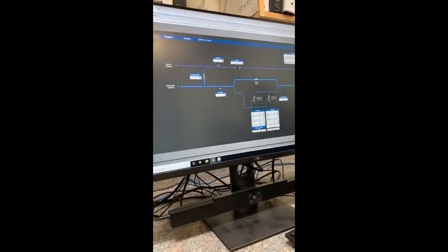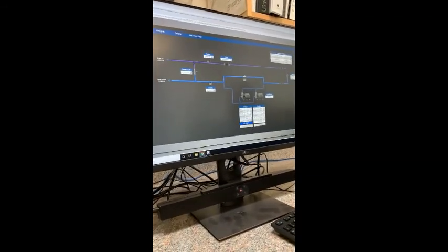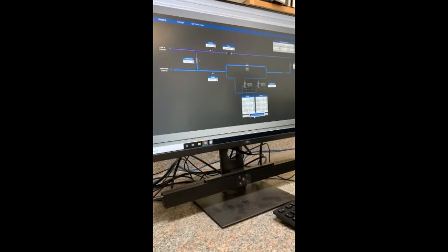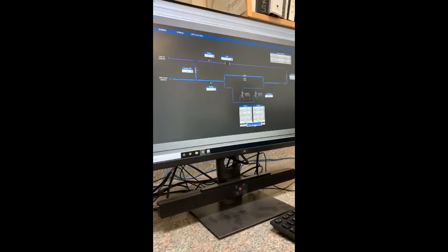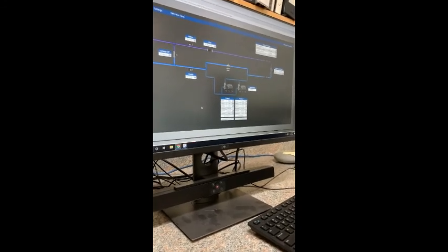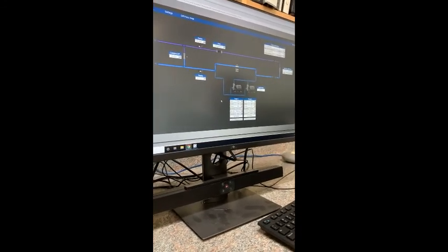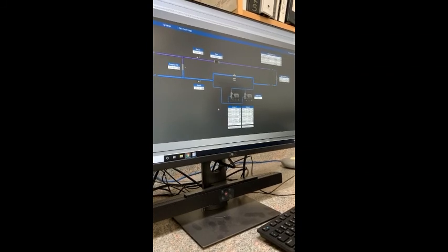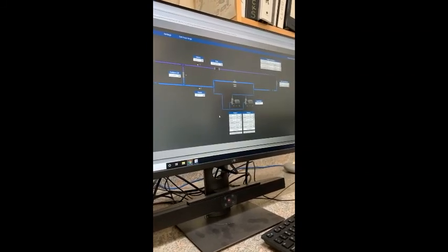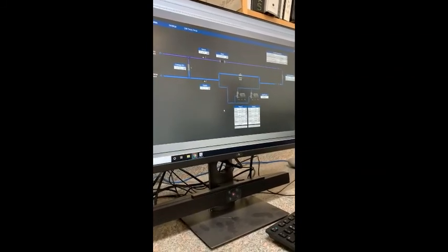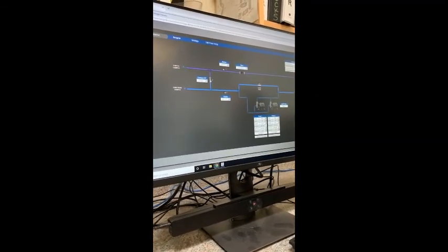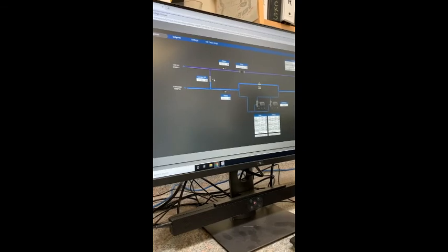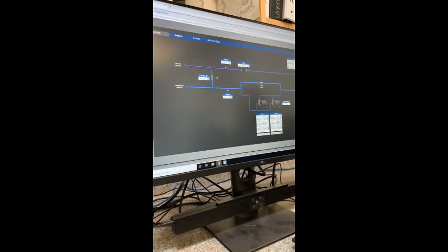So pump 1 had failed to start at some point. Because of that, I could right click on it and click reset pump failure alarm. So now it will try to start the pump. Did we switch it back to auto before? I looked at the screen and it said it was in auto. Okay, I'll check just to be sure.